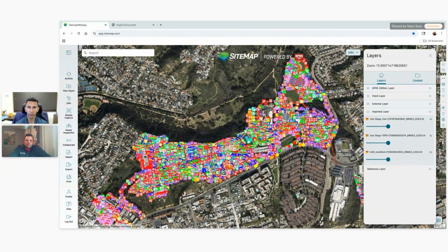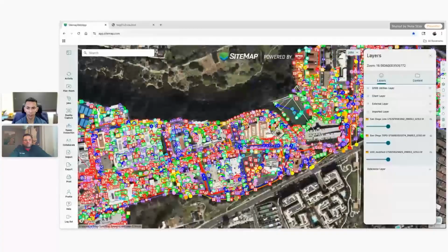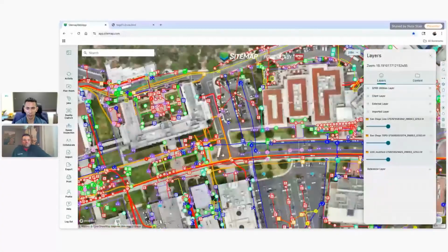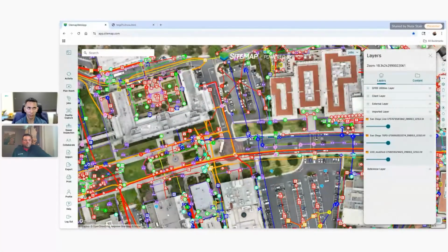Yeah, it's definitely a lot of work on the front end, working with the designer, going through that, we'll call it pack that I send over. Usually it's a mix of CAD and old permitted drawings that we got for the project, and then trying to reconcile the two and see which one is the most up to date. With things like that, it's always tough, because even with a map like this, like Nate mentioned, you're going to have to call dig alert right before you start digging, as it's required by law.